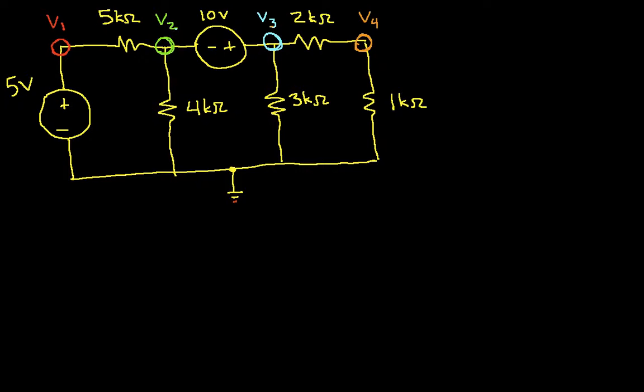Okay, so we've actually completed step 2. In one sense, we're already halfway done. Now the next thing we need to do is look at each of the nodes and use the connections to the nodes to get equations that we can solve. We have 4 unknowns, V1 through V4, so we'll need 4 equations. So let's start by looking at node 1.